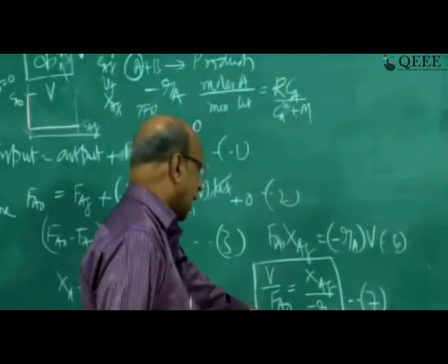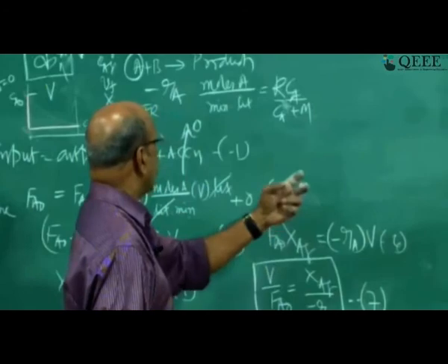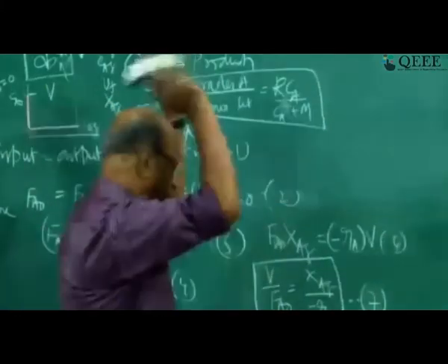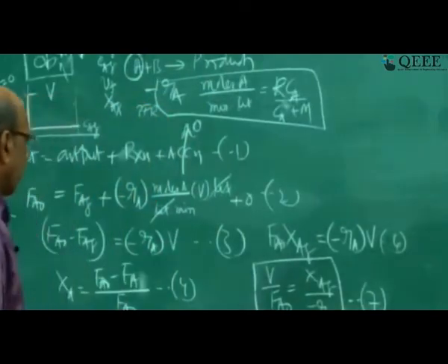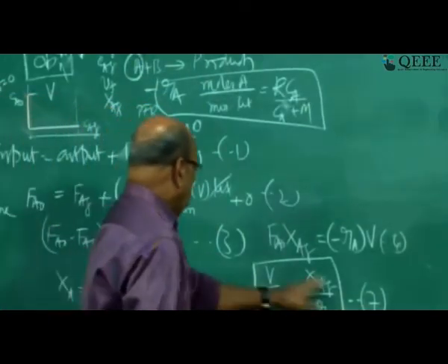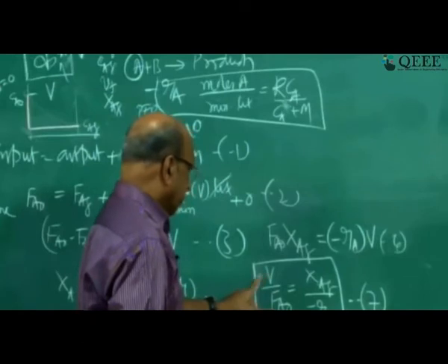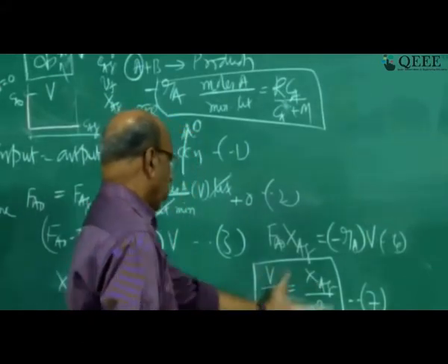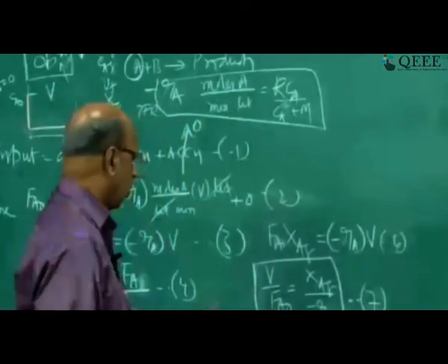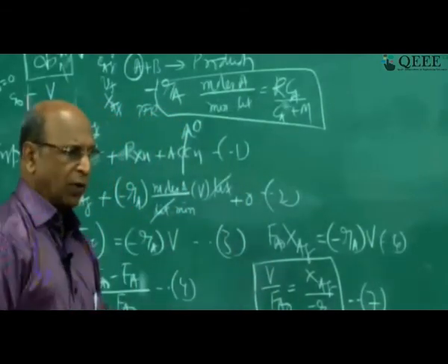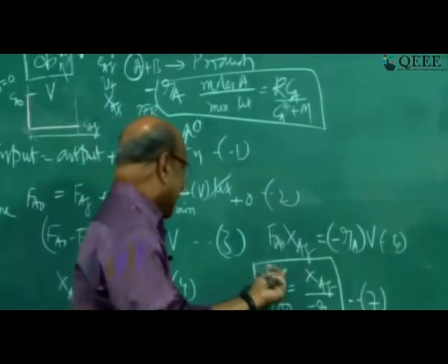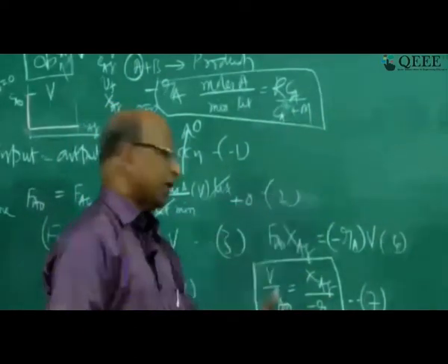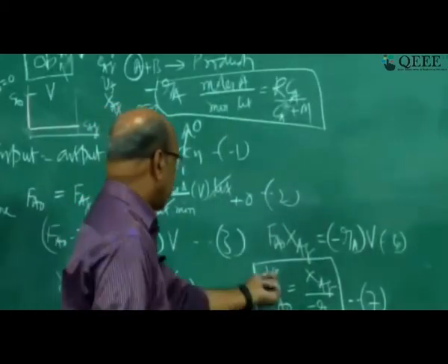This minus Ra can be simply K into Ca, or it can be a complicated reaction like this, or it can have many complications. So now, if you have to calculate the volume, I should know XAF, minus Ra, FA0. So there are 4 variables, at least 3 you should know before calculating the other one. And for a given reactor, that means someone tells that I have a 10 meter cubed reactor, why don't you use that? So already I have V equal to 10 meter cube.